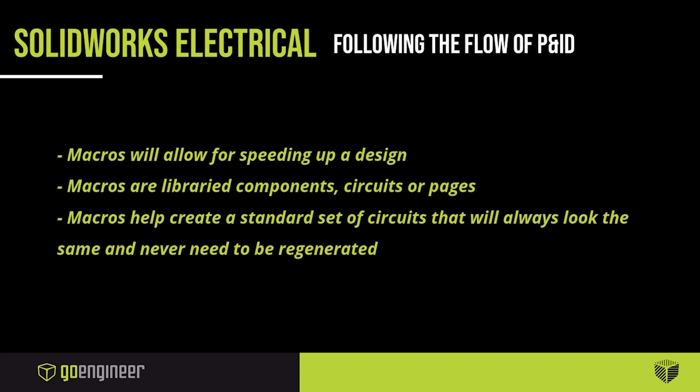Lastly, with the macros, those macros will help to speed up the design. They are also a libraried component or circuit or pages, and macros can help create a standard set of circuits for others to use so that they always look the same and you're never having to regenerate them. So hopefully some of these tips and tricks will make your life easier.